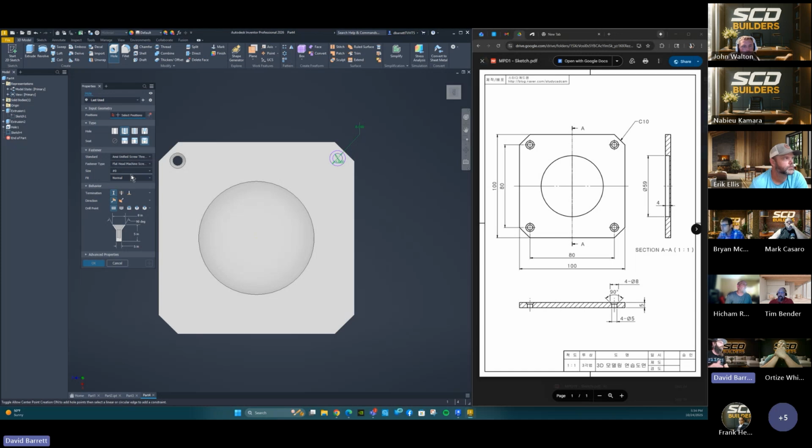Okay, get back into the hole tab. We're going to do another one. Okay, let's go through all the, it's pretty much all set. You got it. It's going to do the same thing. So what you can do up here is on this very top tab of the properties tab, once you bring up the hole, it says last used, which are the dimensions we used last on this hole right here. So we don't really need to do anything. All we got to do is select it at this point, and it's done.